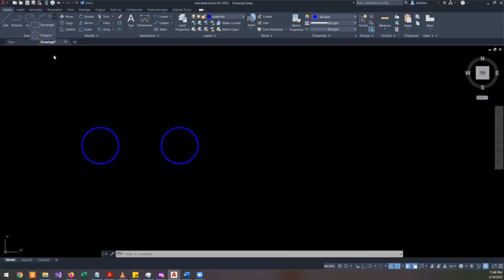Okay, let me demonstrate what this polygon is. Now I have the polygon command. By the way, I think it is POL for polygon. Yes, it is. POL is the alias. Right. So let's take the number of sides to be 6. So this is like a hexagon.